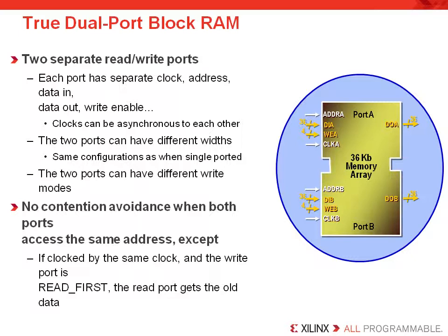RAM when writing. It is also very important that you remember that you can perform a simultaneous read and write or a write and write to the same memory location. Both of these operations can cause data corruption, however, so you'll have to make sure that your address and control signals are stable and as you planned them to be during an operation so that you can avoid data corruption. The dual port functionality also allows the two clocks that can connect to the block RAM to be asynchronous to each other. Now this facilitates the block RAM's use as a FIFO a great deal.